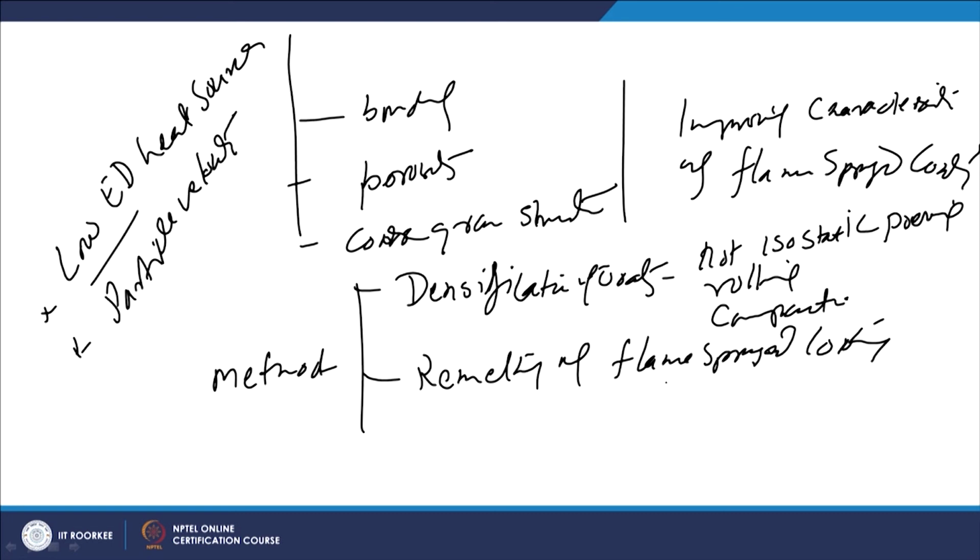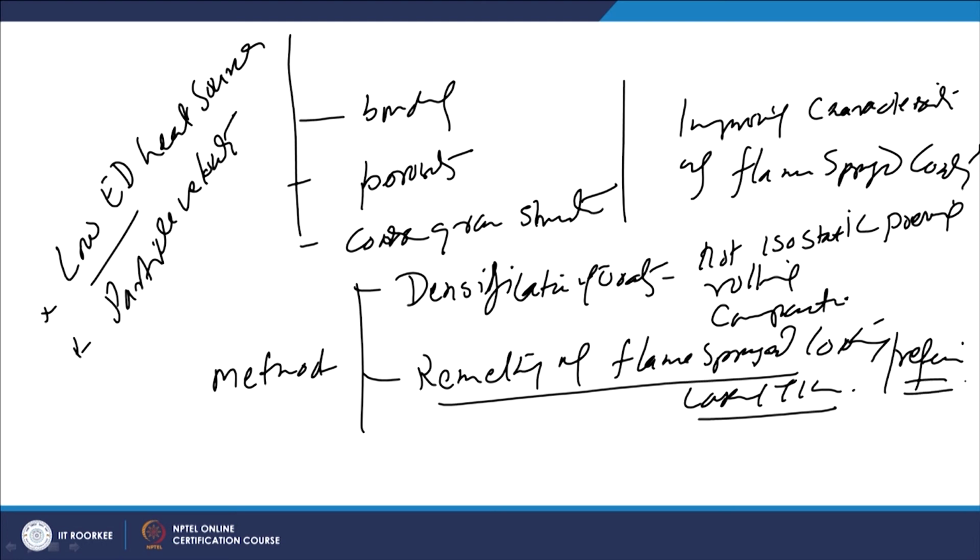So, remelting is facilitated using the laser or the TIG arc. Whenever the coating is remelted, the heat source is of higher energy density. So, this in turn facilitates controlled melting as well as rapid cooling, which in turn refines the grain structure, while densification reduces the porosity and improves the bond strength.